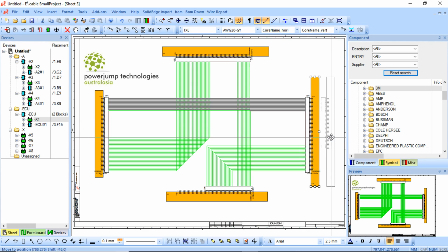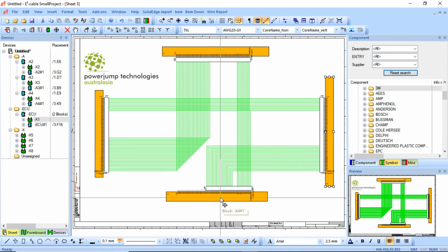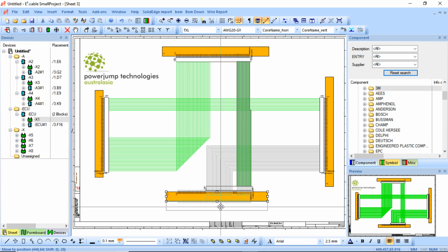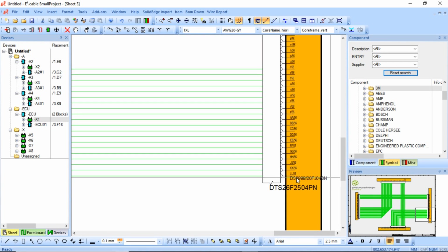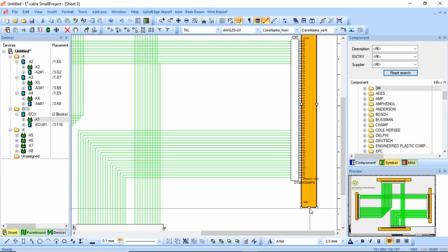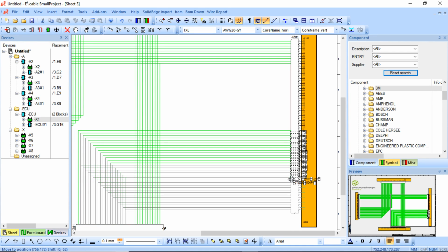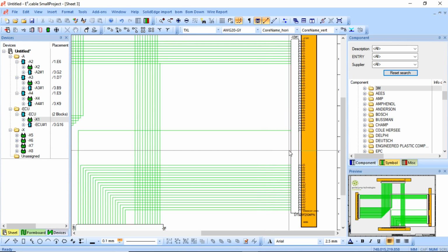As you can see, if you require more space and everything else, you can create it quite simply. As well as that, you can actually move these pins. So if I extend this block out for argument's sake, and I want to change these bottom few, I can simply move them down to a more suitable position.